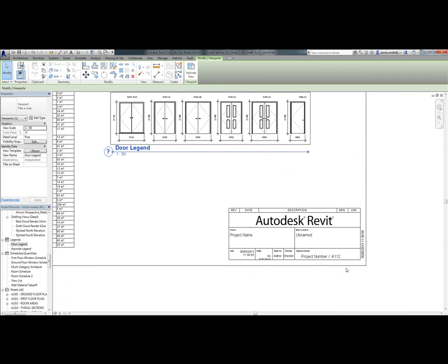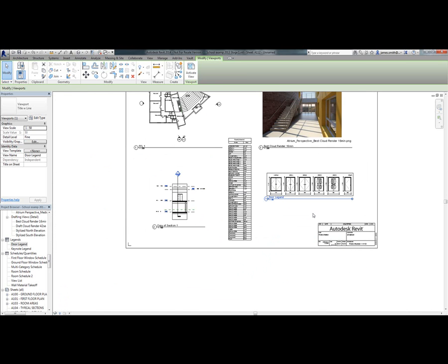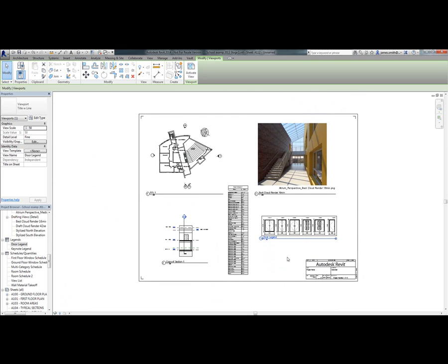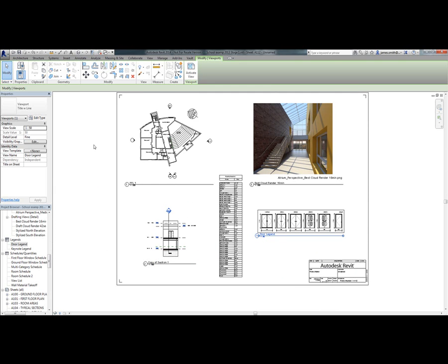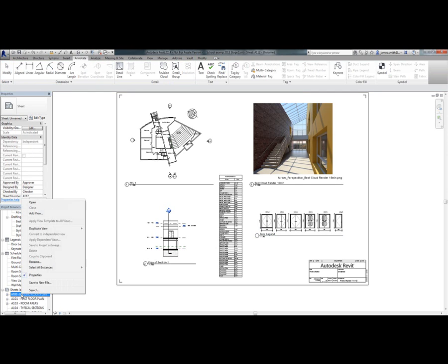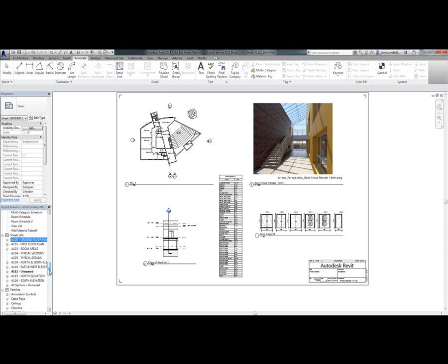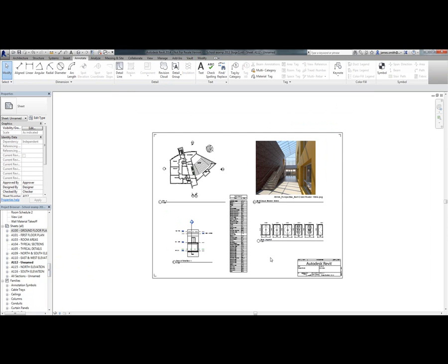You've also got your title block down here at the bottom, so you can add all your author, who it's checked by, the project number, and any other details or fields that you feel you need to add to your project. But then this is completed, and then you can save this out and print this drawing out. So you can go through. You can also duplicate drawings if you wanted to make slight amendments to them, so it'll save you having to go through and actually manually create them each time. And that's a complete overview of how you can take a short design and implement it into a project and then create the drawings in which you can send out.